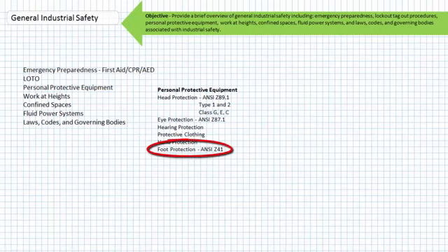Foot protection. Industrial environments are especially unforgiving on feet, so it is a common practice to wear safety toe boots with oil-resistant soles. The safety toes prevent impact injuries, and the oil-resistant soles aren't destroyed by oil, in addition to providing slightly increased traction on oily surfaces. The standard governing foot protection is covered in ANSI Z41.